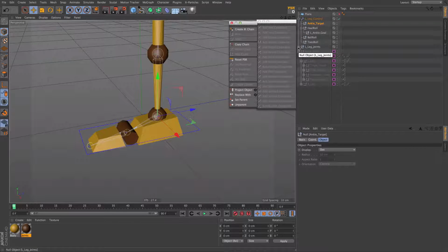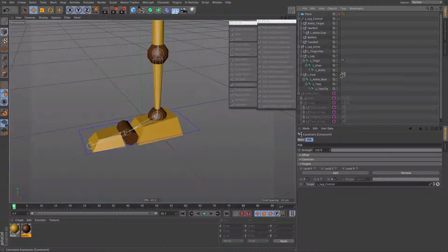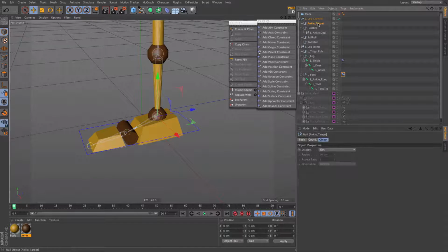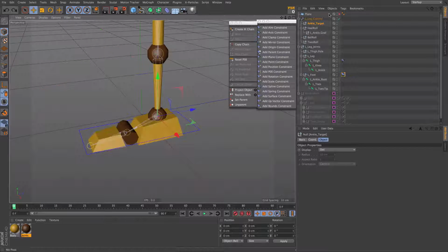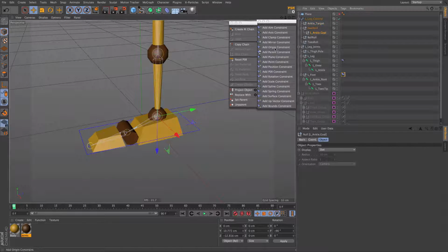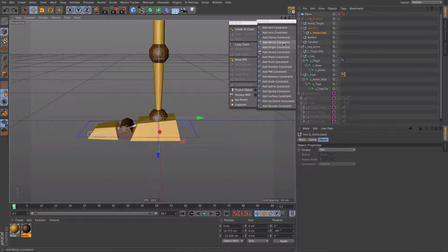And let's open our joints hierarchy here, and on the constraint of the foot, let's change the spline with the new null that we created, the ankle target. So this null is taking the foot with it, the goal is taking the IK leg with it.